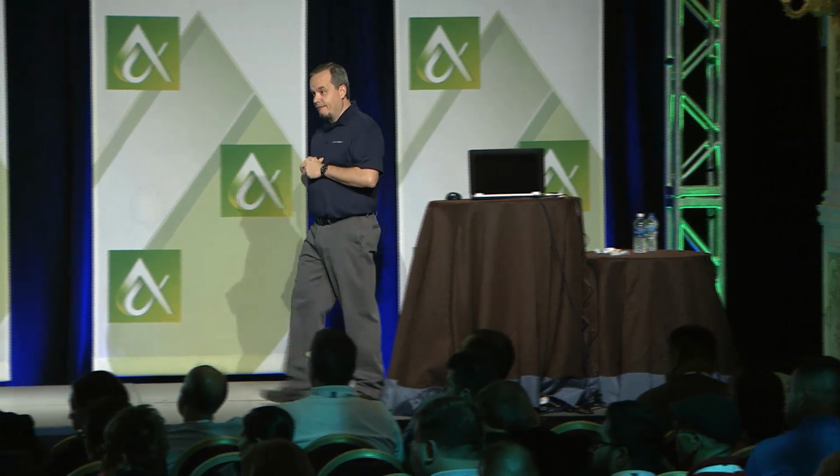All right. So I think I'm doing okay on time. Just want to throw out, are there any questions so far based on what you've seen? Yes, sir? The points you inserted at the corners previously in the table, are those points snappable as insertion points or only the base points? Okay, so the question was, the points that I put on the table all the way around, are they snappable as insertion points, as in when you use the snap to insert? I don't believe so. No, I have to go back and double check, but still that one grip is the insertion point, the base point. Yeah, good question.